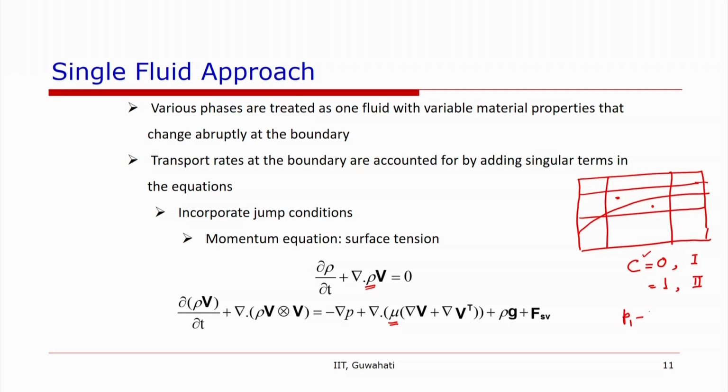The next part is the dynamic boundary conditions at the interface. The first one is the tangential stresses. If there is no Marangoni stress, then the tangential stress is continuous, which is inherently built into this system of equations. The stresses are going to be continuous. So, fine. The other boundary condition is the normal stresses, P1 minus P2 is equal to sigma kappa, which comes because of the surface tension.